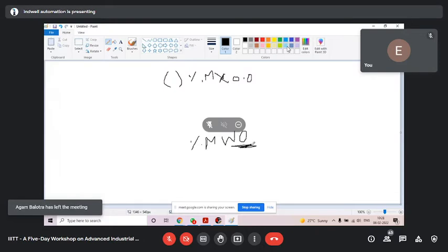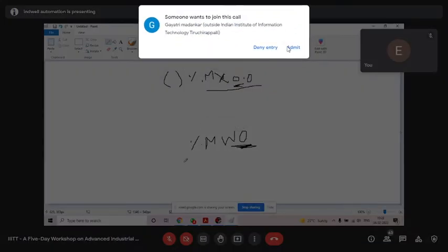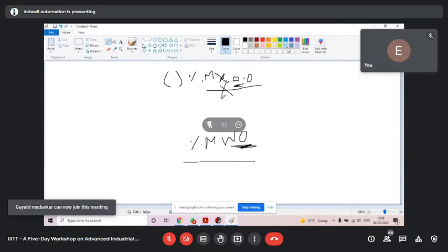You see, this word location 0, already a bit of it you have used. So if you are using a bit, don't use its word. If you use its word, don't use its bit. That's why in our program we have used %MX0.0. So I had told, don't use %MW0, or else what will happen?